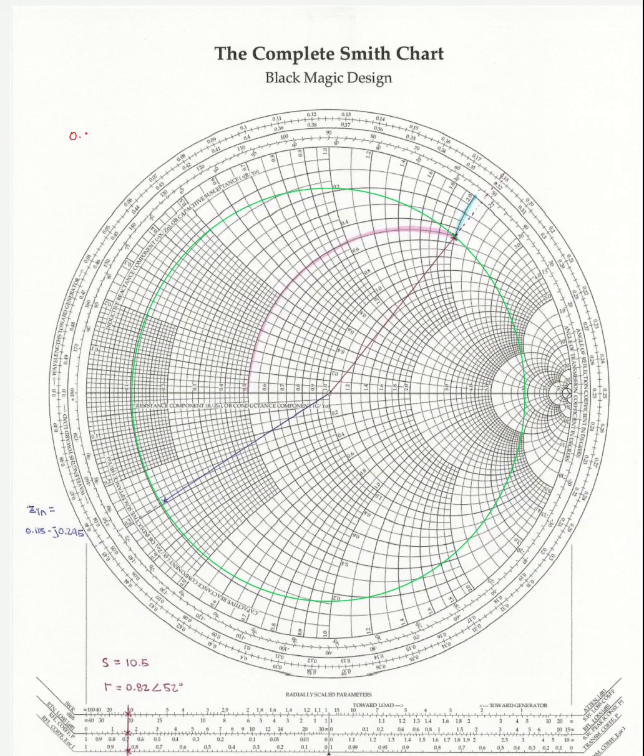So using 0.5 plus j2, we'll notice that we have the resistance component and the reactance component, and so we simply have to map that on the Smith chart. For the resistance component, we go along this axis and find 0.5, which we find here. And for j2, which is our reactive component, because it's plus, this just means go up in the inductive region. We look for a 2, our 2 is right here, and follow that down. Same thing here, follow this up, and we look for the intersection point, and this will be our ZL, or our normalized ZL.